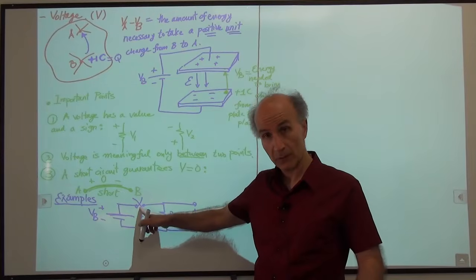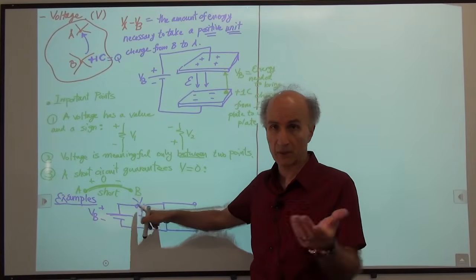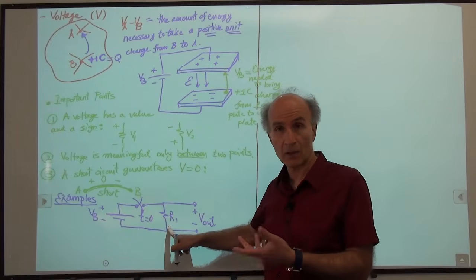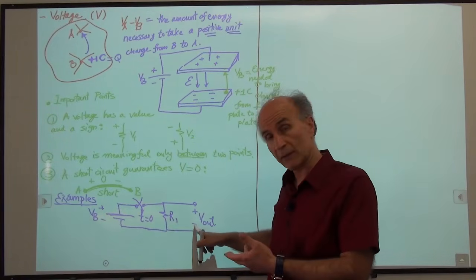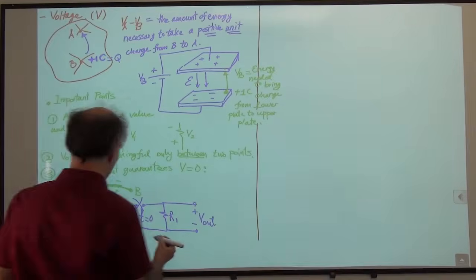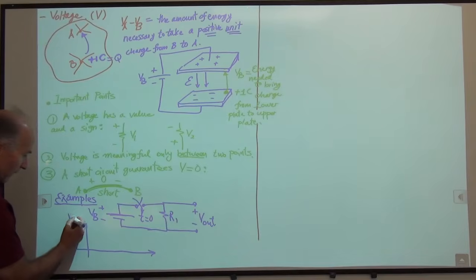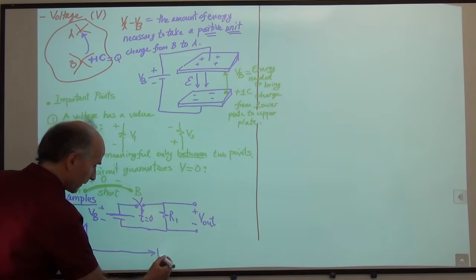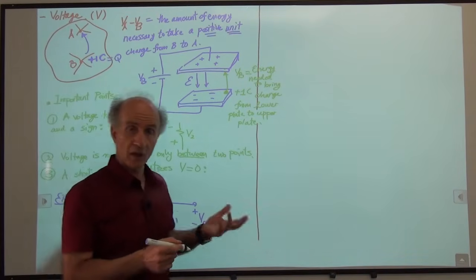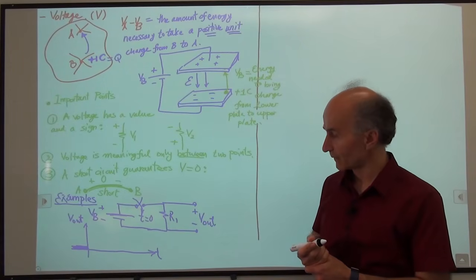Before the switch closes, before the switch conducts, there's an open circuit here, right? When the switch is not conducting, no current can flow this way. If no current flows through R1, Ohm's law says R1 has no voltage across it. So V out is 0. So before t equals 0, the output voltage is 0. So let's try to sketch that here. So we have V out as a function of time, and before time 0, there's no current passing, the switch is not conducting, it's off, it's open, so R1 sustains a 0 volt difference.